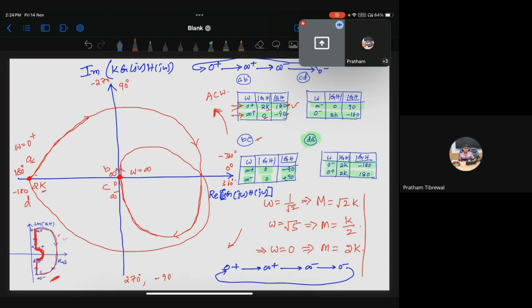Yes, exactly. Now you see, what the Nyquist plot basically says is, if you keep varying your omega from 0 to infinity, how the response changes. So basically, if you are given an open loop transfer function, if you just substitute the values from 0 to infinity and plot both the real and imaginary points, you will get this plot only.